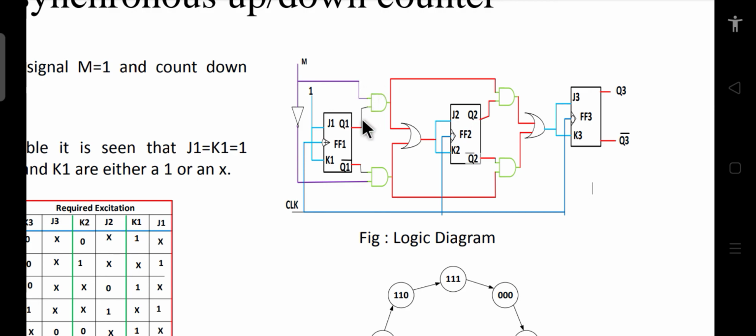Just to design this circuit, to find what should come here, we have done all these steps. Depending upon the problem statement, you have to design the circuit. When we design a synchronous counter, we know we have to use certain flip-flops, and we can decide the number of flip-flops very easily. We can decide how the clock pulse will go: all the flip-flops will be triggered simultaneously by a single clock pulse. But then we have to decide the in-between circuitry, and to decide that we have done all these steps.